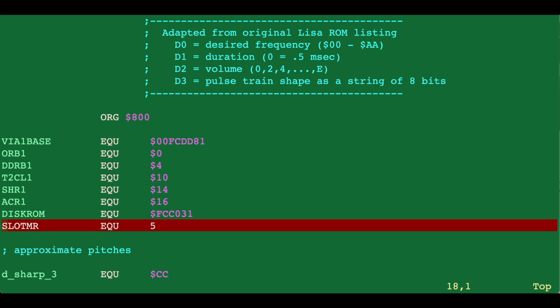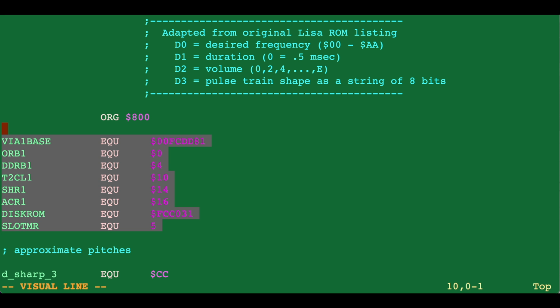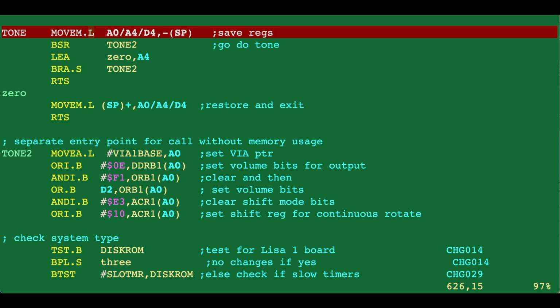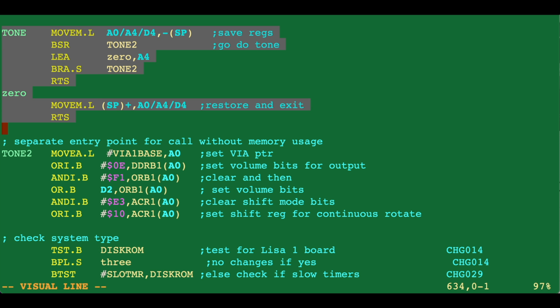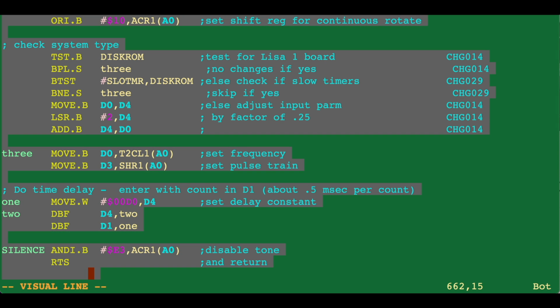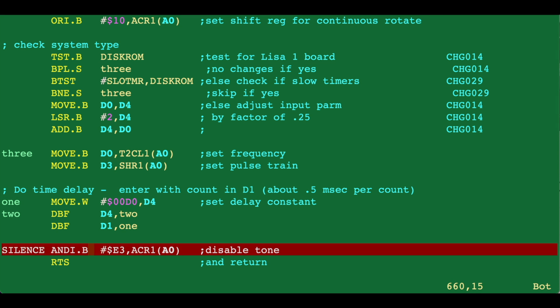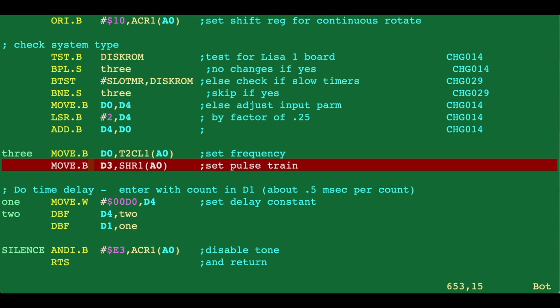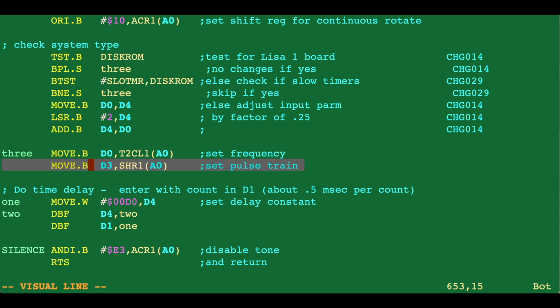This helped a lot because all the constants required for addressing the VIA chip were already set for me, and I did not have to calculate them based on the hardware manual. And the actual steps to load VIA's shift register, the same which I had to write manually in my Arduino exercise mentioned earlier, were already there to use. The only modification I made was to replace the hard-coded 50% duty cycle square wave with a variable, which I could set in my score.